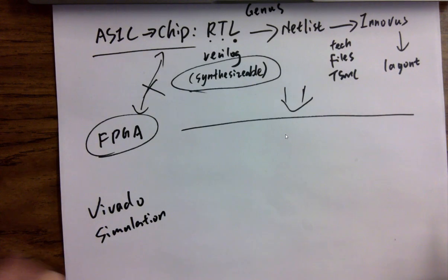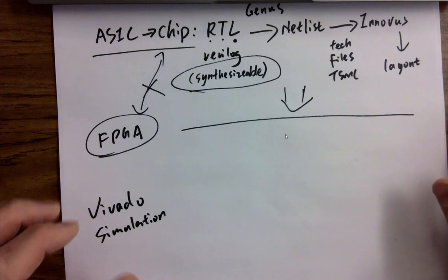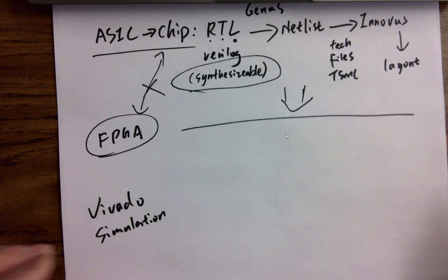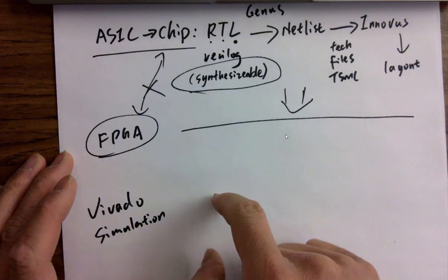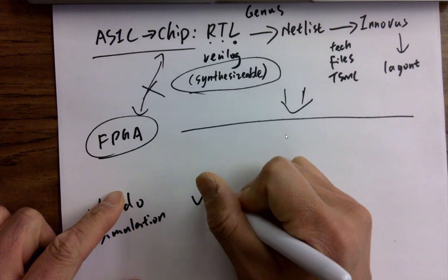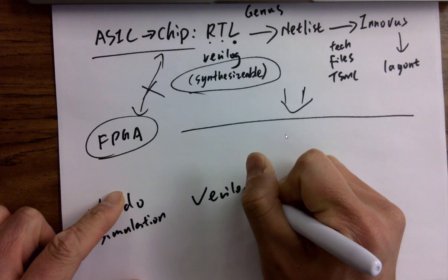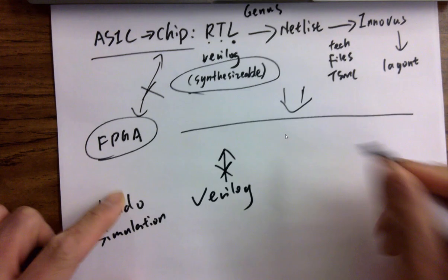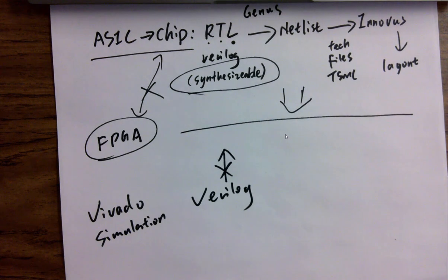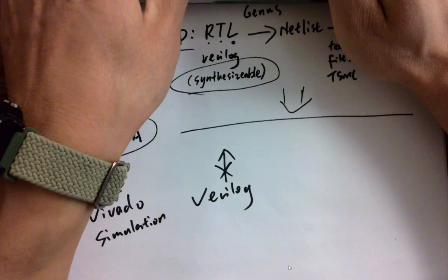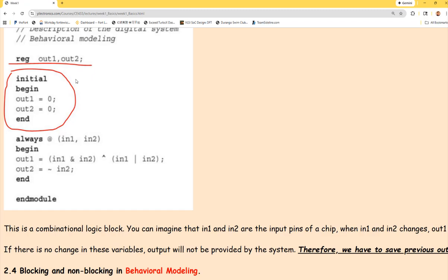You write Verilog code, and it has a high level of tolerance. Sometimes even with syntax errors, it's still able to go through and show you the simulation results. However, that code, all this Verilog here, probably cannot be used for hardware design, like FPGA or ASIC. For the ones we have over here, a lot of times some of the platforms don't take initial begin.